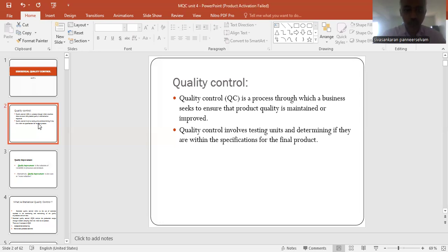Another way, we can say quality control can be defined as checking the primary specification of the product. Say, for example, you are designing a shaft of diameter 10 and length 250, whether the given part is able to match the tolerable limit or not. If it is out of proportion value, then the given part need not be accepted. It will go under scrap or wastage. So in this way, quality control can be better understood with a lot of simple examples.